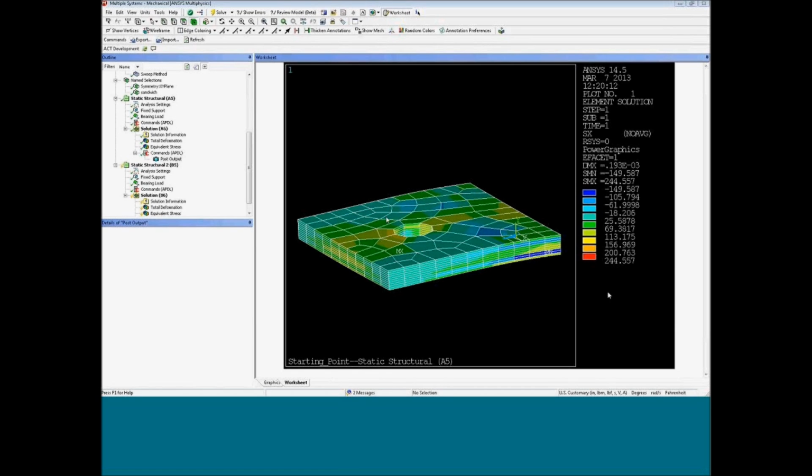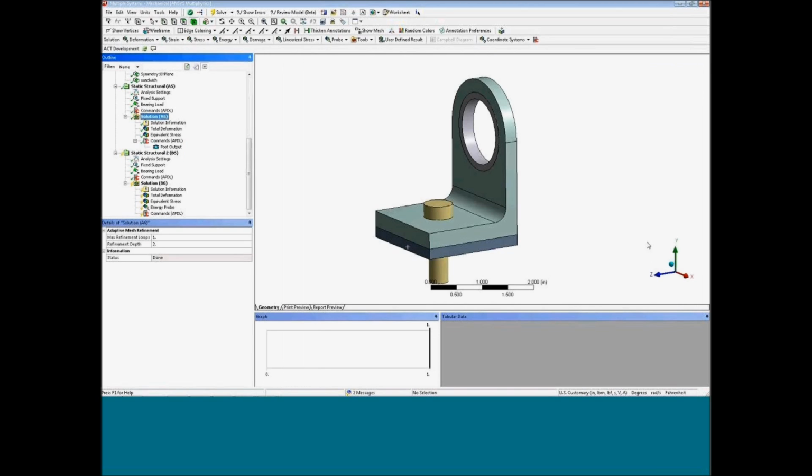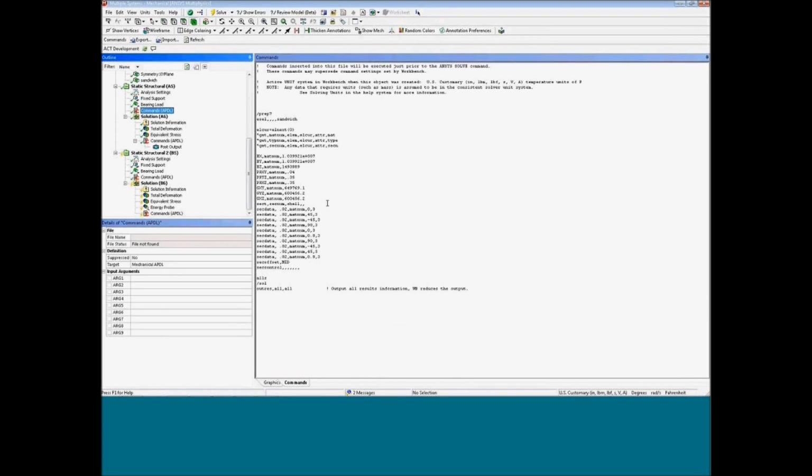All right. So then let me go back and show you a couple more things that we can do with the command blocks. The next thing I want to do is go into this command block here where I define the section properties. In here, these are the ANSYS commands for putting in a bunch of different layers, and they're that amount thick, and then there's a whole bunch of layers.